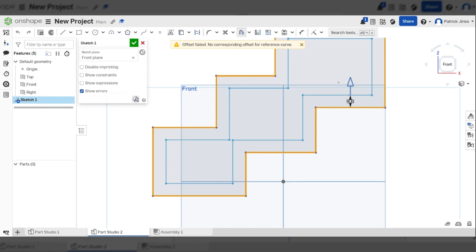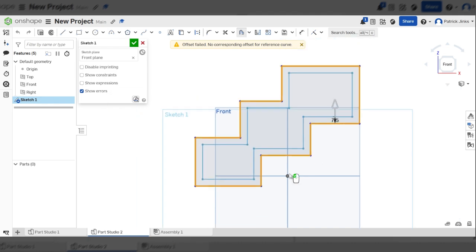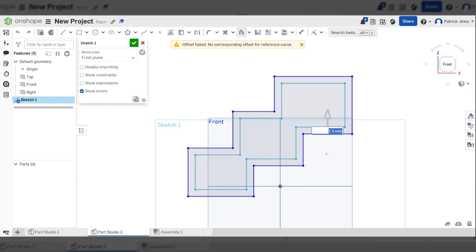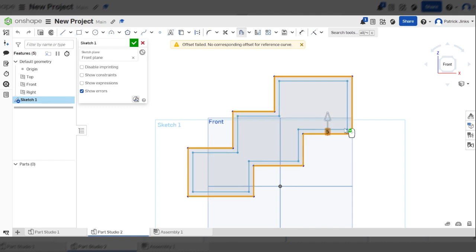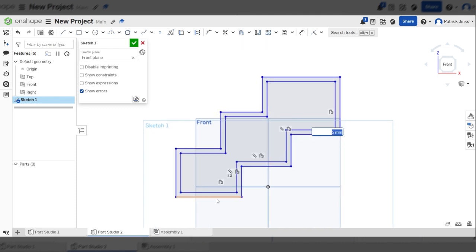With an offset tool, you can't clip through, but I can get it to that. And I can set this to, let's set it to 5 mil. And then all I need to do is click once. You'll see with the cursor, I've got the green tick to click when I'm done. And it's put me a nice border.